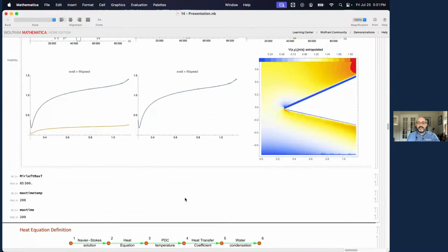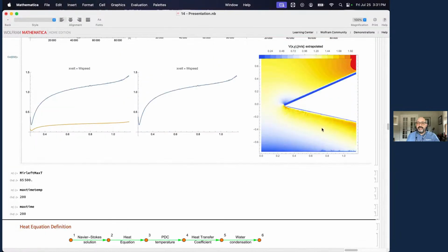I generate an extrapolation function, and then you have it. Now you are able to get any result of the Navier-Stokes equation at other velocities, right? You cannot extrapolate too much. You need to be careful, because if I say that the actual wind conditions were 100 meters per second, obviously this is not going to be correct. But in the small range, you could use the linearization techniques that I'm describing.